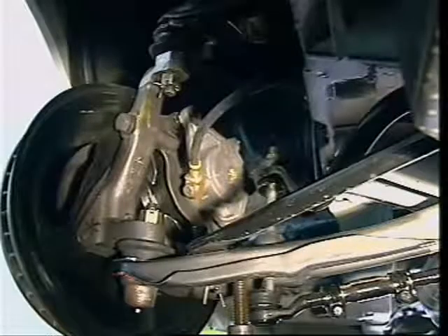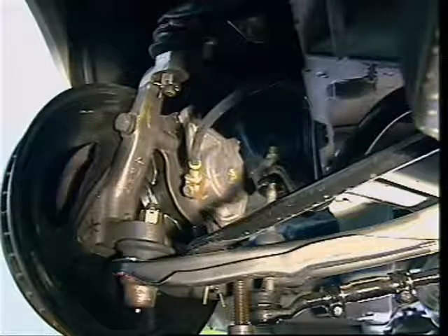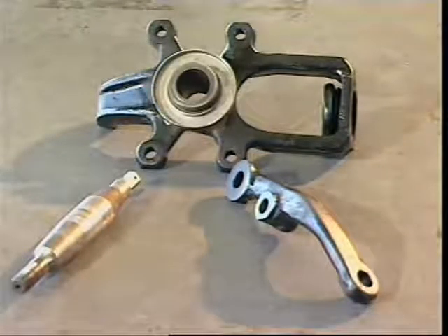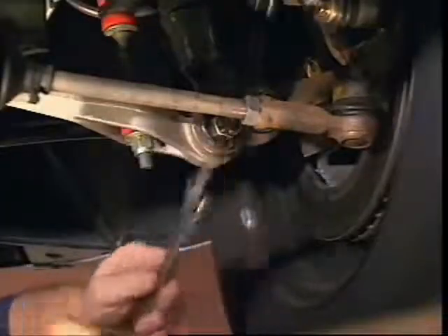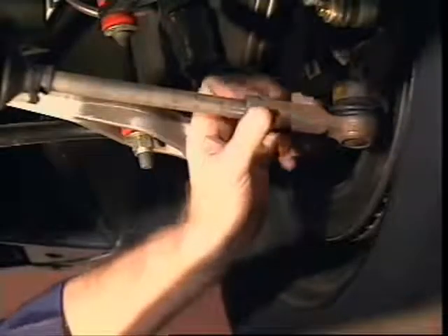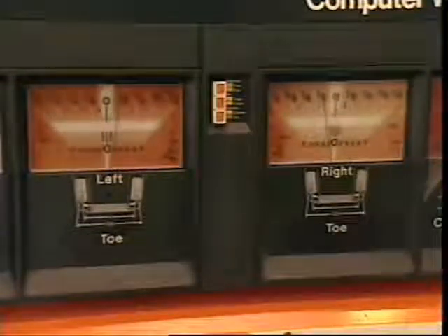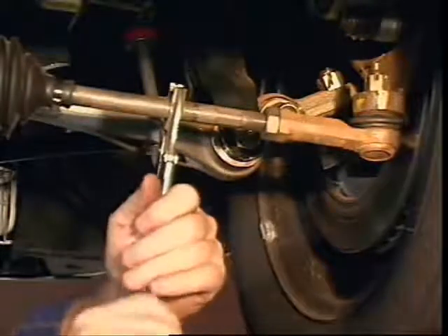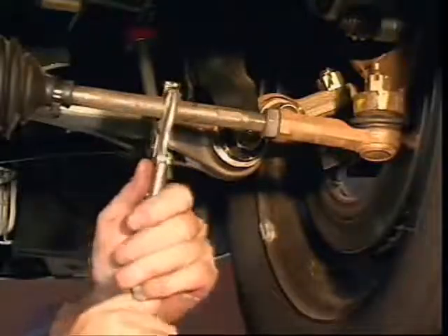The lever, the stub axle and the stub axle carrier can be forged as one piece and can be referred to as a knuckle. They can also be made as separate units and assembled to form one piece. Each steering system makes provision for adjustment of the linkage to achieve the manufacturer's recommended toe setting. The track rods or tie rod ends are threaded to provide for their lengthening or shortening.